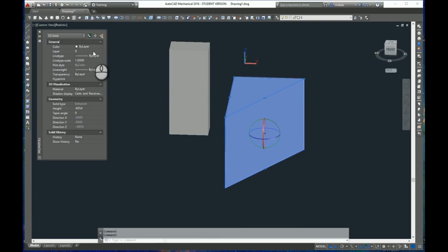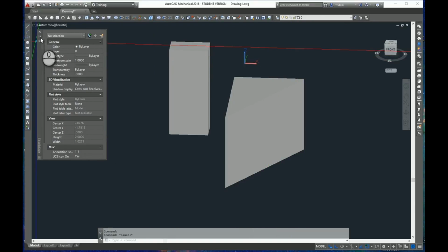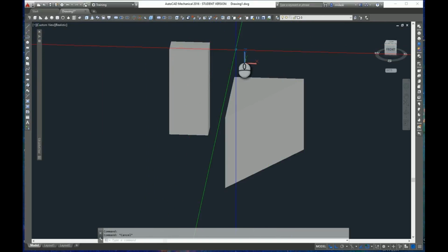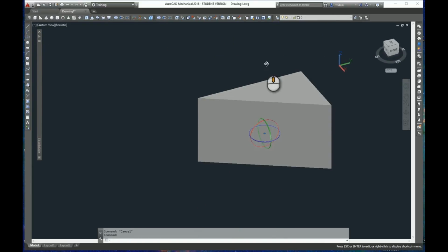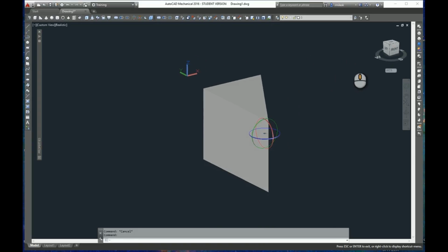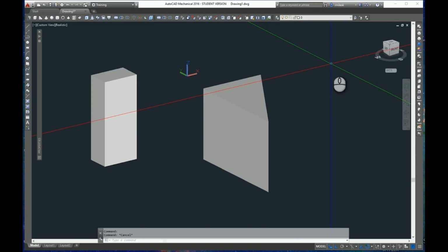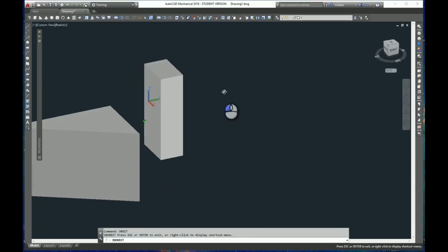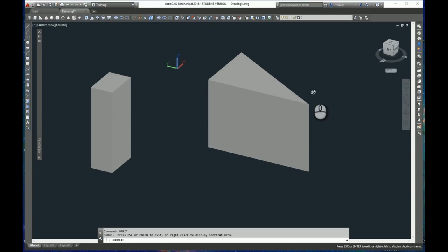A 3D solid. Now, there are other ways to move around AutoCAD, to kind of navigate around in 3D space. What we were actually using earlier when we held down the Shift key and the mouse wheel is called the Orbit command. You can access this command by typing orbit. However, if you're inside another command, holding Shift and then holding down the mouse wheel is the better way to do it.